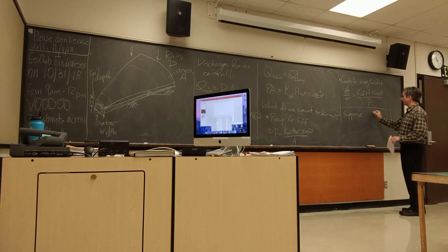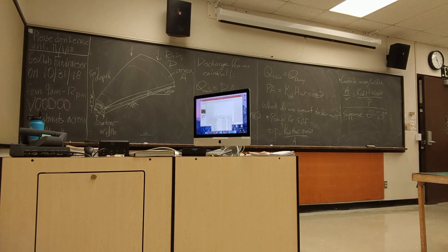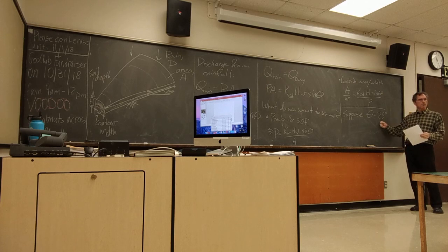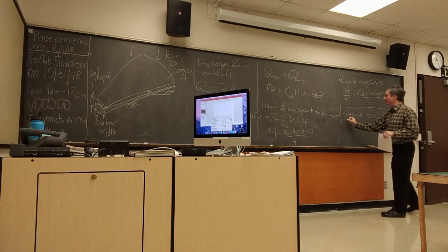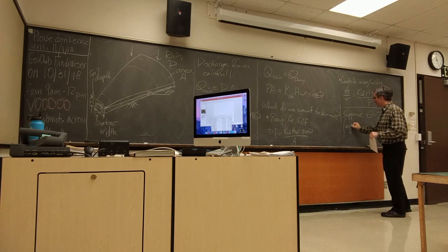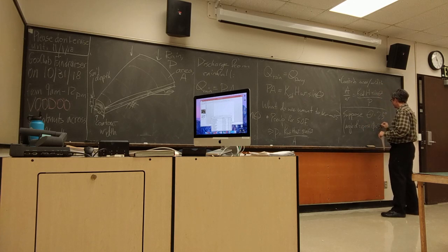Suppose my angle theta is 25 degrees. Pretty steep. Not ridiculously fall-off-the-hill kind of steep, but pretty steep. Is that raising any alarm bells for anybody if we're talking about saturating something that's 25 degrees? Let's say my angle of repose, just to maybe throw a hint at you, is 37 degrees.